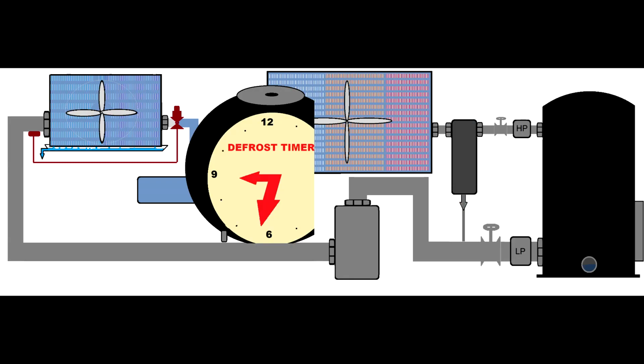The defrost based on a timer is not a precise defrost, yet it is a defrost. The timer wouldn't know the value of humidity percentage in the room. So after the defrost, you have to allow the water to go onto a drip tray and to be eliminated, and then you will restart the refrigeration cycle.